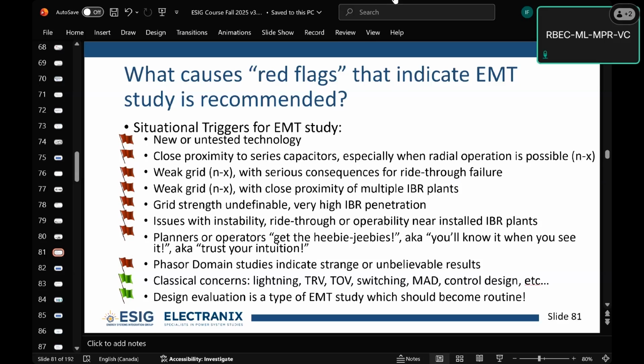And I think that's part of the process as well, of experience. That bothers the simulation engineer doing it as well, by the way. When I'm working with junior engineers, best practices can be bent. We can change the rules for these studies, and we do all the time, depending on what you've learned from other studies. Another example would be, how are you going to model the transmission lines? Are you going to use frequency-dependent transmission lines or not? And how far do you go back? Are you going to model transformer saturation or not? Are you going to aggregate or not?